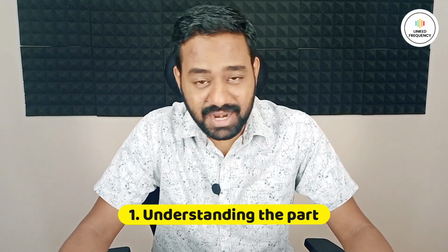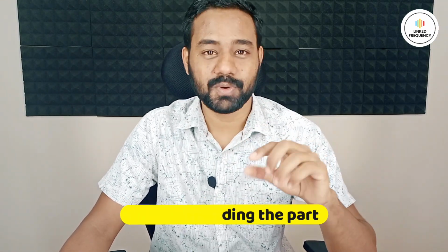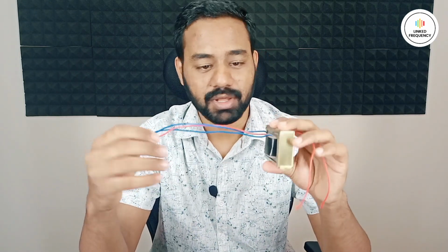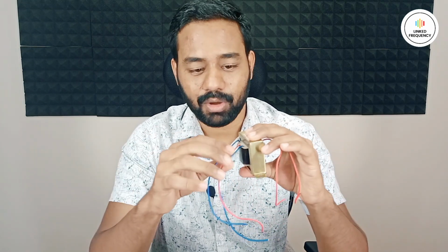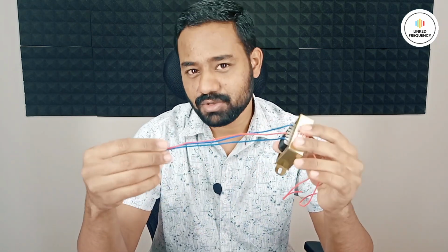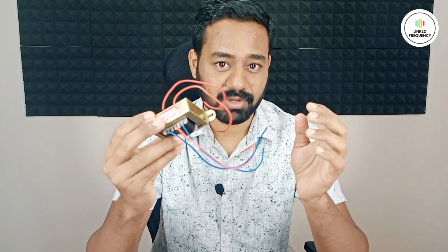So let's get started. The first step is to understand the schematic symbol and also the dimensions of this particular component, which is a step-down AC transformer. This transformer is mostly used for designing AC to DC power supplies. A linear voltage power supply is where you provide an AC voltage, which is 230 volt 50 Hz, to the input, and you will get a center-tapped output, which may be 12-0-12 or 9-0-9 or maybe 5-0-5, based on what type of transformer you want.